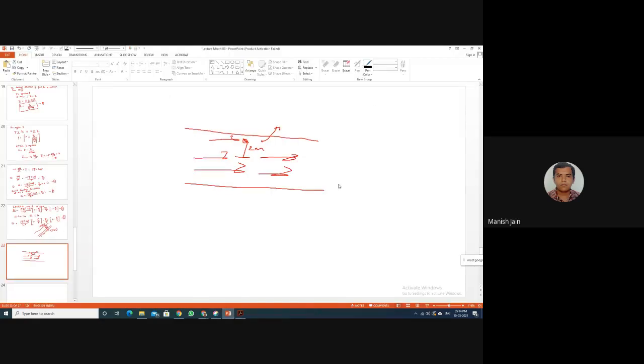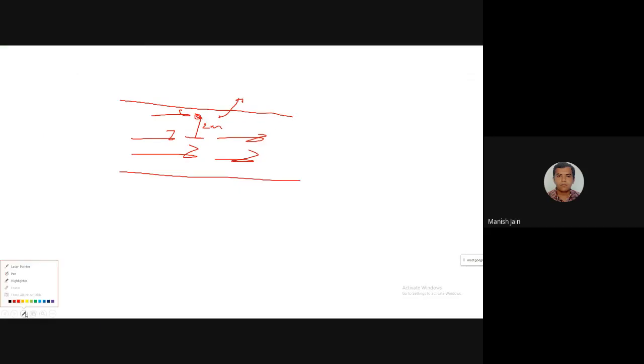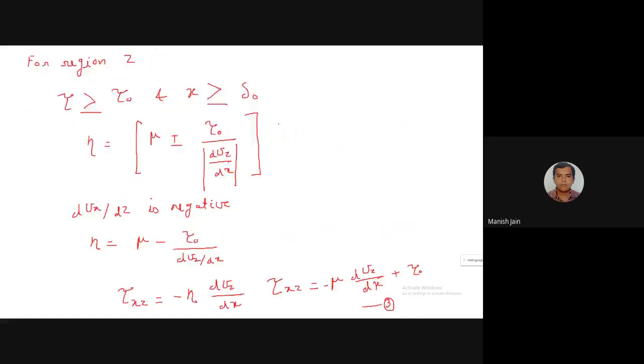So it is not easy to use the micro level fluid mechanics at large scale operation for turbulent flow. For laminar flow it is easy. But whatever equations we solve, whatever derivation we had done, that is only for the laminar flow. If you are solving the turbulent flow, then for each point the fluid may move in this direction, in this direction, in all three directions, and it may also depend upon time. So the solution becomes very typical, and you have to solve all the equations of motion with time also, and that is also second order partial differential equations. So the solution requires a huge amount of computational power.